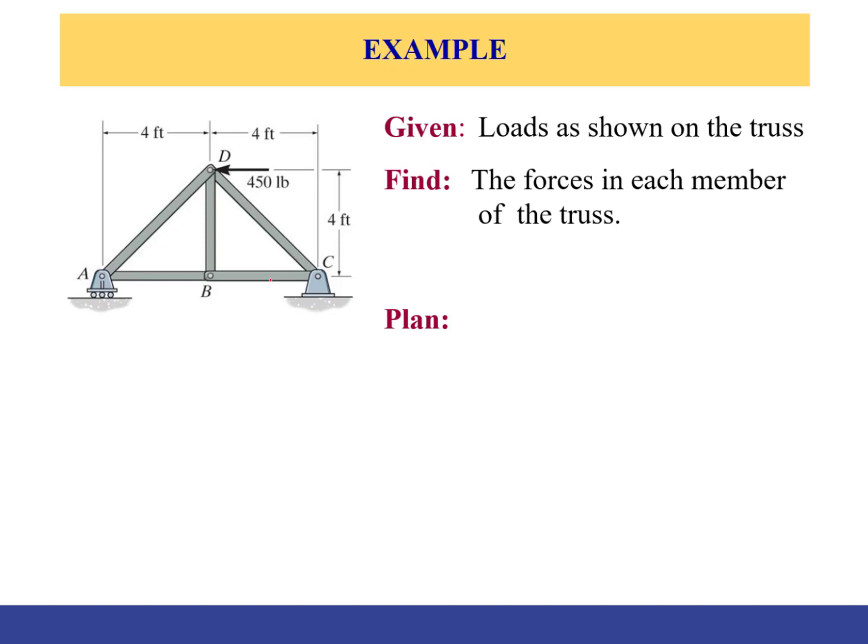Well, let's take a look. What we have, let's take a look at this. CB and BA are two collinear members which share a joint at joint B, share another member which is not collinear with them, and that joint B doesn't have any reaction force, it doesn't have any external load, therefore I can drop that.